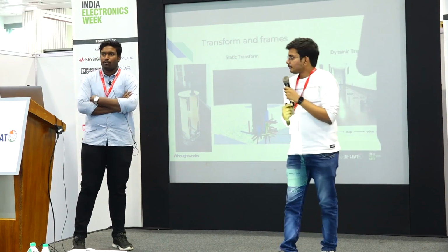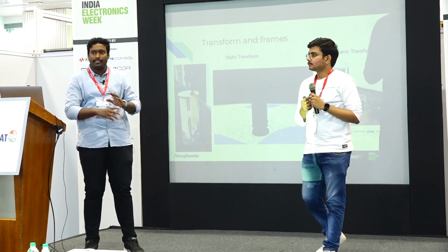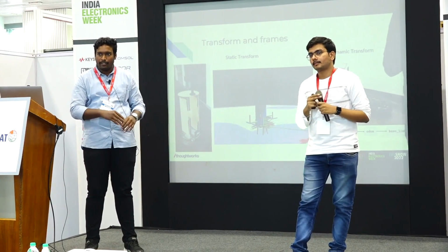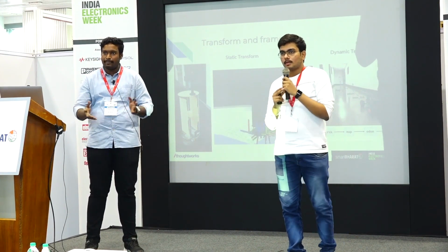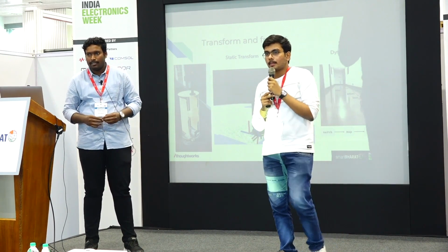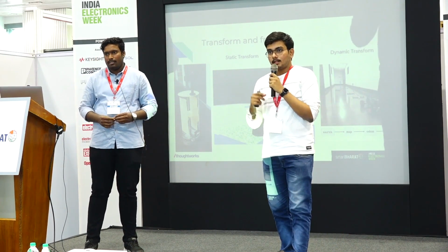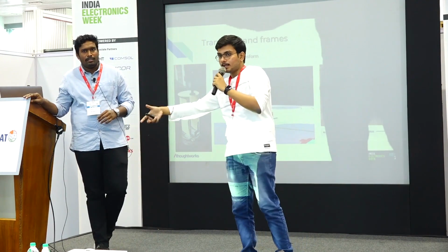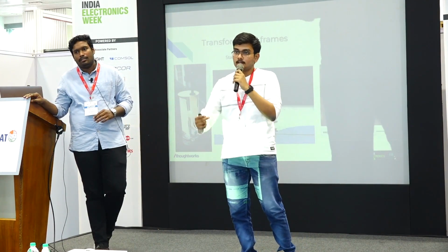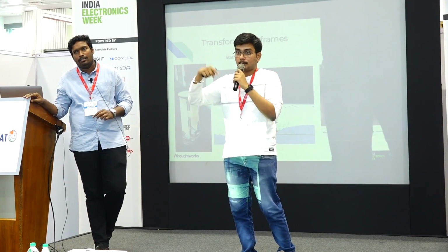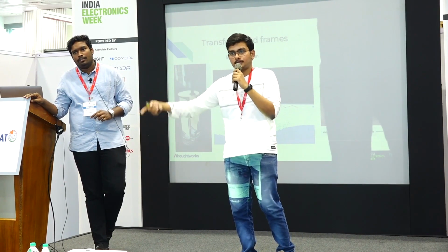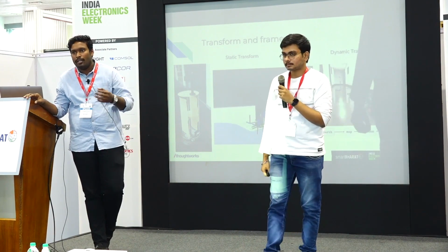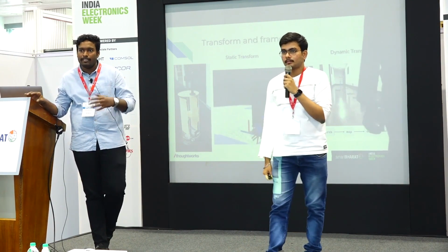And you also have the odometry sensor, right? The odometry sensor tells you how far it has moved from the origin, so you can compute from that. State estimation uses the acceleration and distance from the IMU. But even if we take the bot and keep it in a new place, when it moves a certain distance in the environment, it can localize itself on the map at the new position. And you also have sensors like IMUs and GPS; you can fuse all this information to get the actual position.